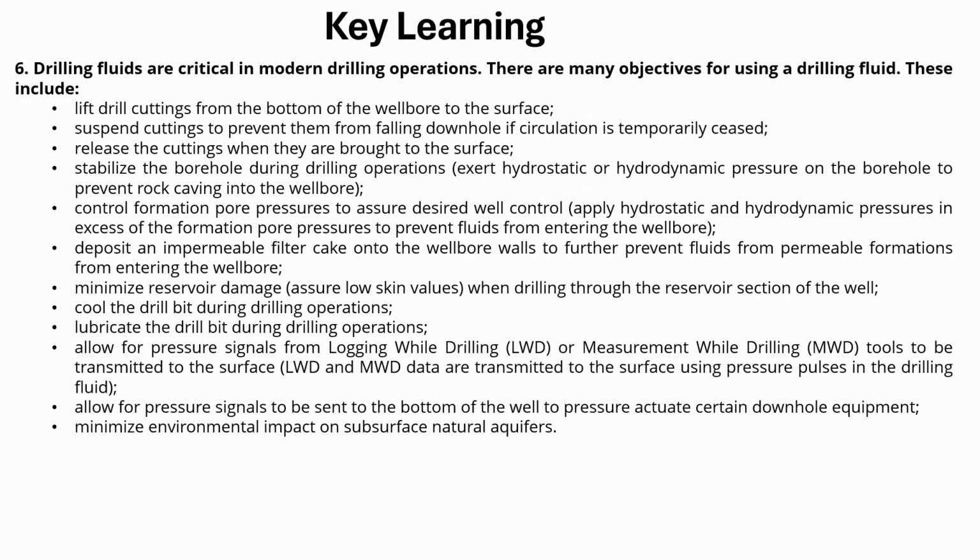This slide summarizes 2 topics. First, it lists 3 major bit types used in the drilling industry: milled tooth tricone, insert tricone, and fixed cutter bit. Second, it reviews the well control system, including the accumulator and blowout preventer.